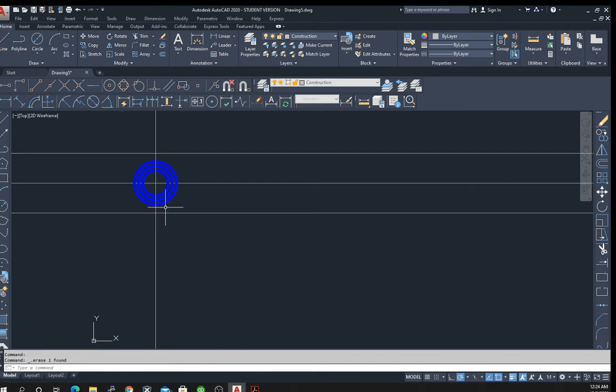And again, we have to go back to our object lines. We put in a circle of 1.5 diameter. I chose radius there. Diameter 1.5. And then 3/8 and 5/8. So 1/8 is 0.125, so 3/8 is 0.375.